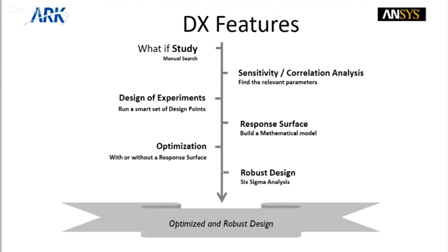Once I complete this flow, I will show the demonstration of the what-if study on my computer. So in what-if analysis, this is just a manual study that comes by experience. So what should I change? I should change shape. I should change size. I should change the input characteristics. Let us say for structural analysis, it may be pressure or force or constraints as well, different boundary conditions.